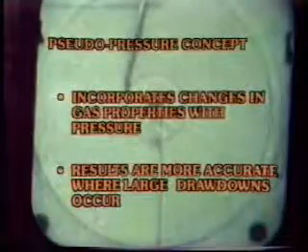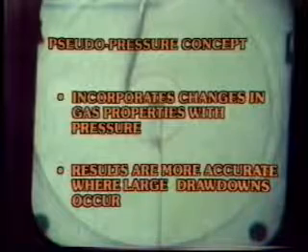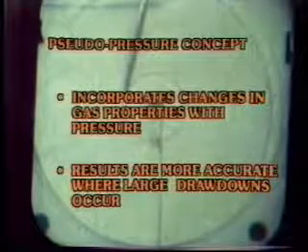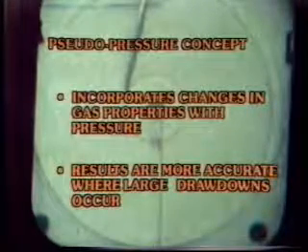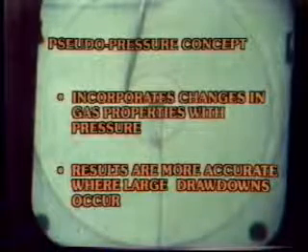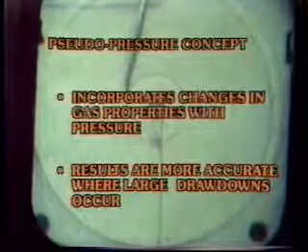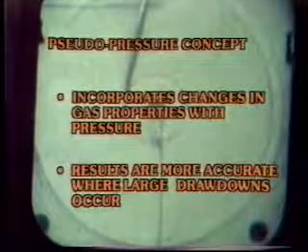In order to incorporate the changes that occur in gas properties with pressure, we introduce the pseudo-pressure or real gas potential. No longer is it necessary to assume average gas property values, and when pseudo-pressure is substituted for pressure in our deliverability relationships, the results will be more accurate. This is especially true where large drawdowns occur. The basic definition and recommended use for the pseudo-pressure concept is found in your course manual.